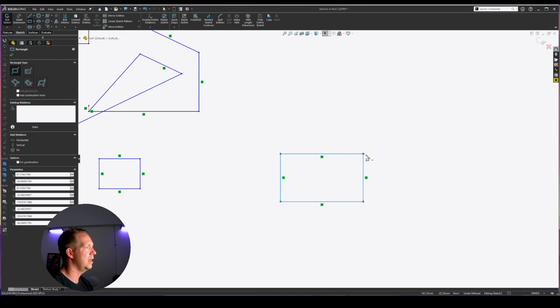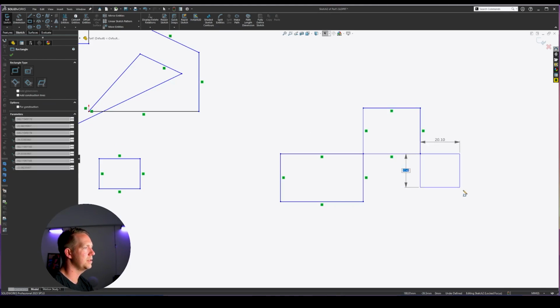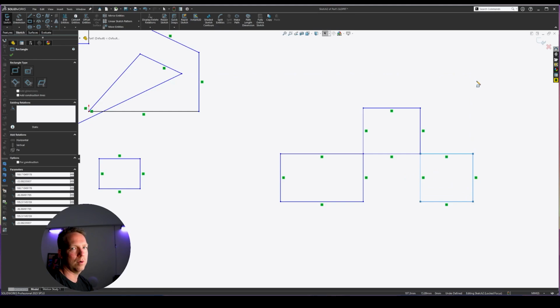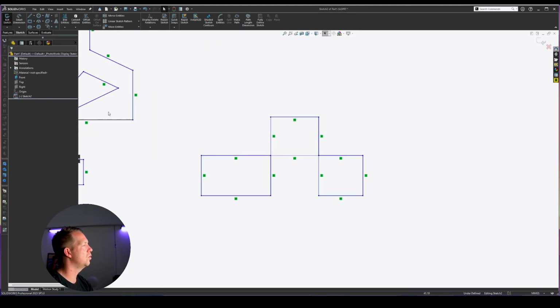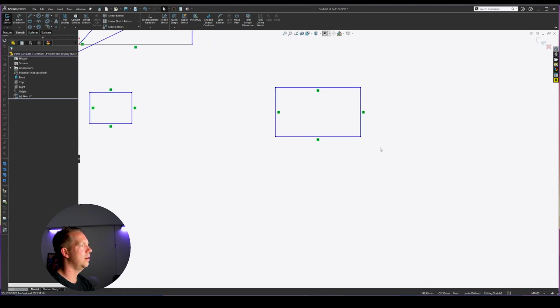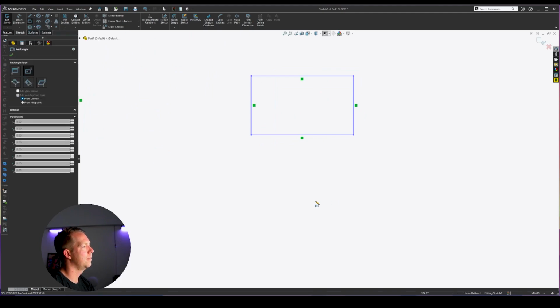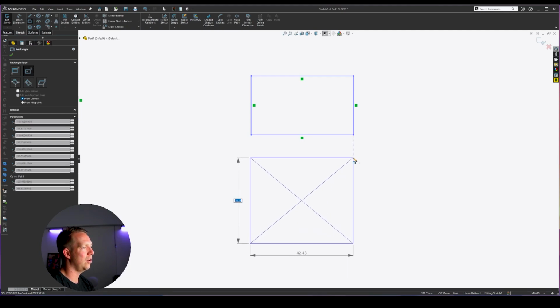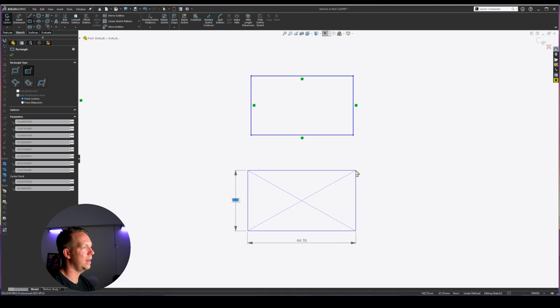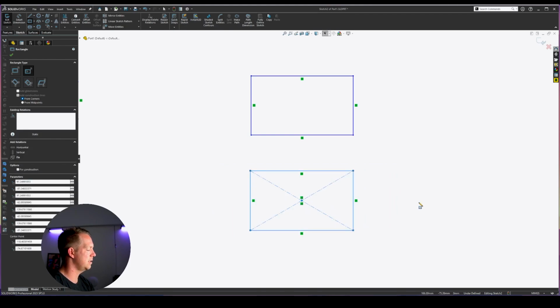And then you can start another sketch and another sketch, and you're creating more and more rectangles. Okay, that is a corner rectangle. Here I'm going to sketch all 5 types of rectangles. The next type is a center rectangle. How that works is it drops a center point and you drag out and you go up and across, and that is creating a rectangle from the center.